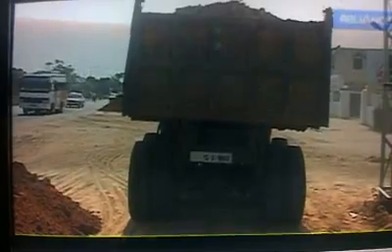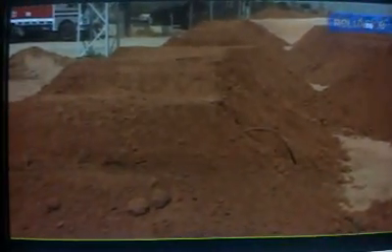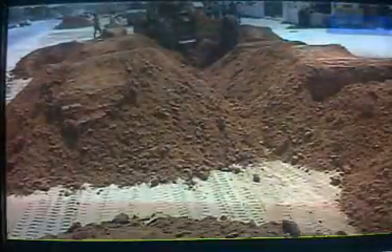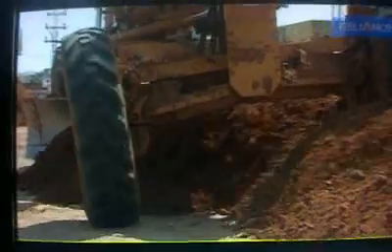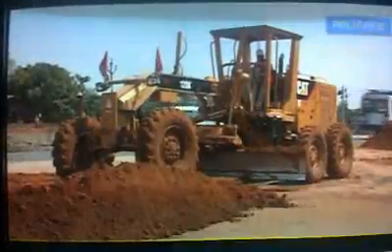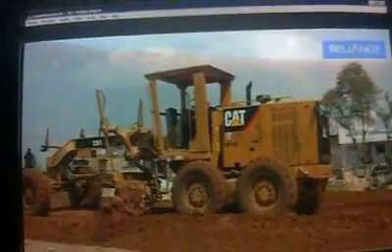For safety, it is ensured that all tipper backup alarms work properly. The tippers dump the soil at equal intervals on prepared original ground. The embankment is constructed in layers of uniform thickness not exceeding 200 mm of compacted thickness, finished by a motor grader. The motor grader blade has hydraulic control suitable for initial adjustment. It spreads the soil so as to achieve the specific slope and grade.